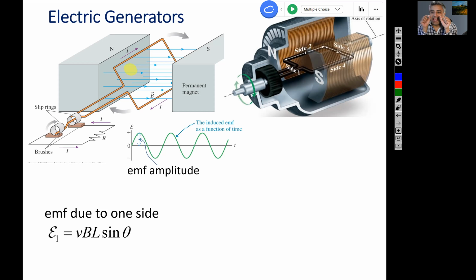So in the motor, what happens? We supply the current. Remember, we plug these devices into the electric outlet, which means current flows through the coil. So when current flows through the coil, what happens? The side of the coil experiences torque, and that's what makes it spin. So current is spinning the coil in the case of motors. But in the case of generators, we are trying to generate current, so we're not supplying current there. Rather, we are spinning those coils by using something else.